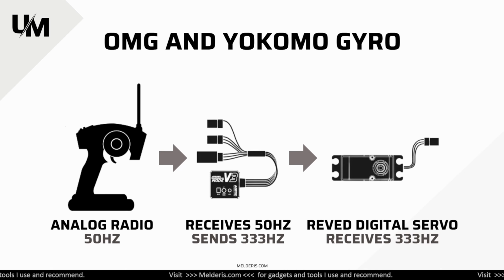So what would happen in this situation? It still would work, but in the long term it won't be a good solution, because in the long term your servo still can die, because it's still receiving higher frequency than it's supposed to accept. Okay. So this is important that you get this information out, what frequency servo you are using.